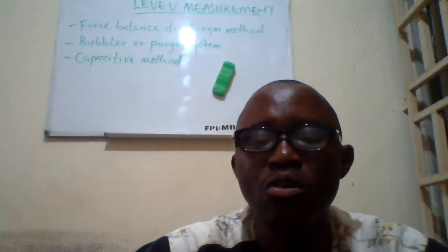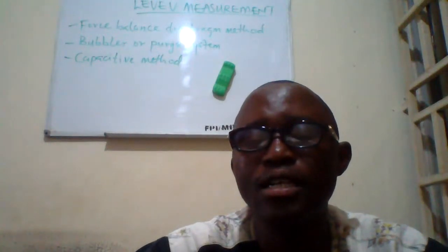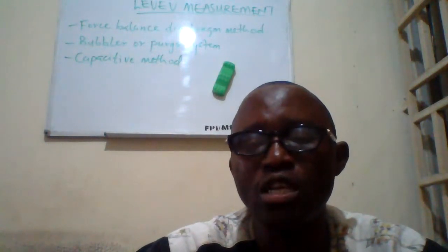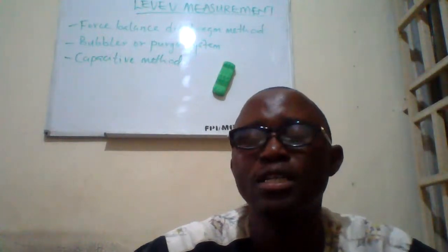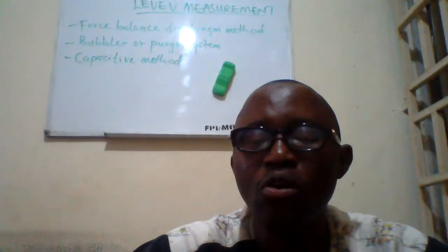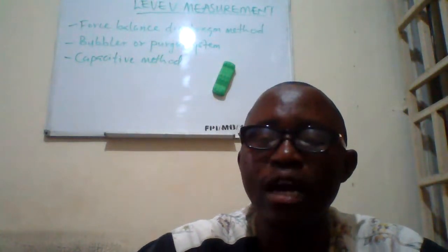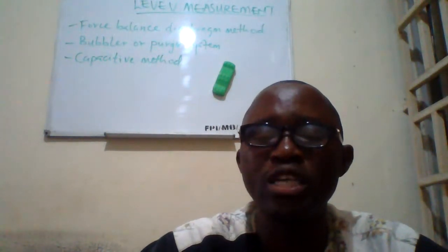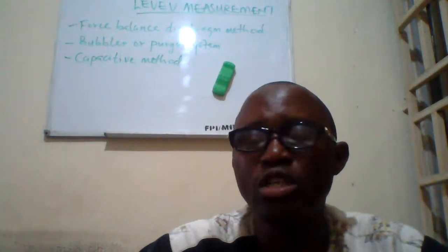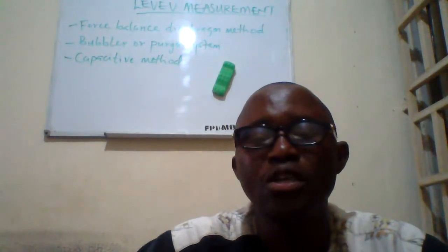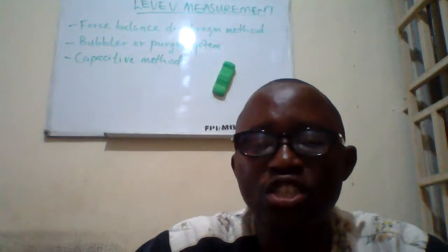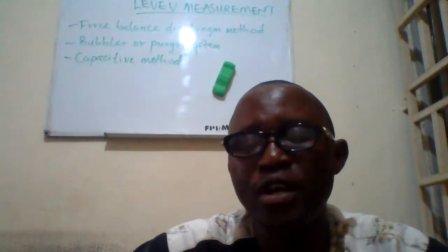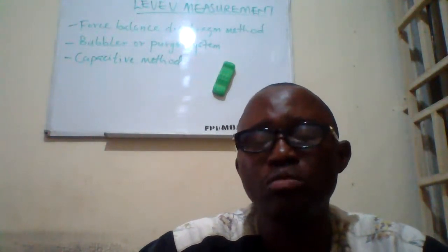There's a small device attached to the tank that is connected between the liquid and the top of the tank. Talk about differential pressure. We are talking about measurement of pressure of two bodies that are related, but have different pressure. So there's going to be a pressure difference between the two parts of the system. And that is what we term differential pressure. The difference in pressure is going to be measured, and the value of the difference is going to be indicated.